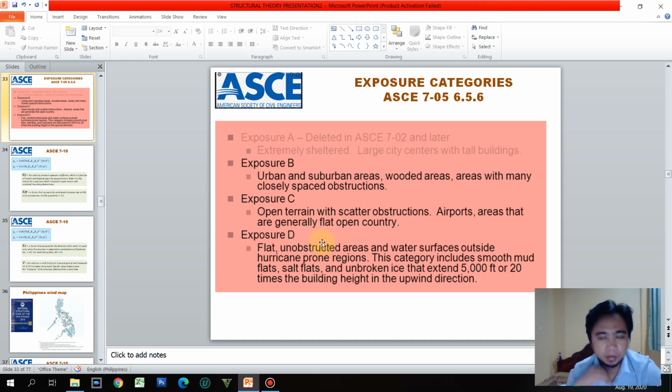Exposure C: open terrain with scattered obstructions, airports, areas that are generally flat, open country. Exposure D: flat, unobstructed areas and water surface outside hurricane-prone regions. This category includes smooth mud flats, salt flats, and unbroken ice that extend to 5,000 feet or 20 times the building height in the upwind direction.